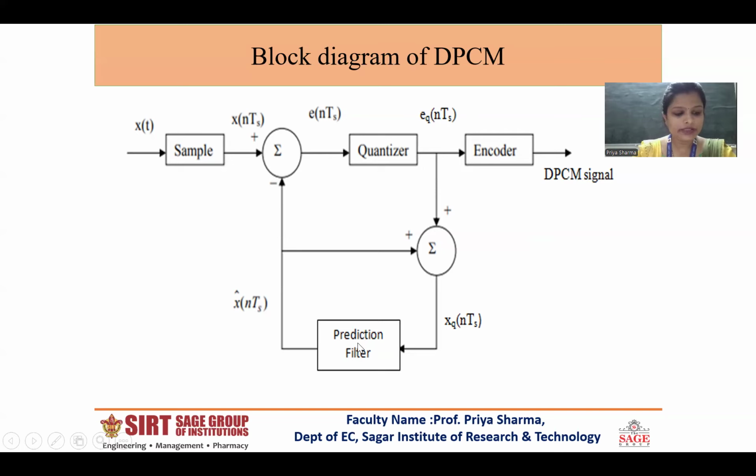An integrator determines it and applies it to the differentiator for comparison with the input signal. Then it is convenient to find whether the next difference signal needs to be positive or negative and of how much amplitude in order to bring the accumulated signal level as close as possible to the input signal. At each sampling time, the difference amplifier compares the input signal level and the accumulated signal level.